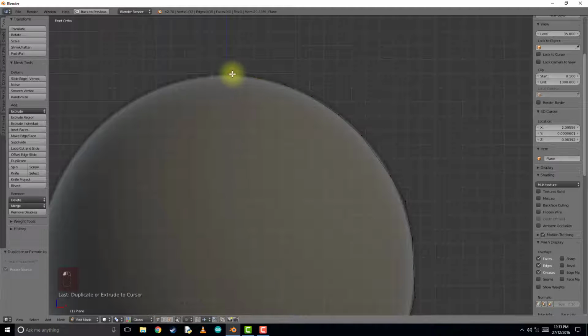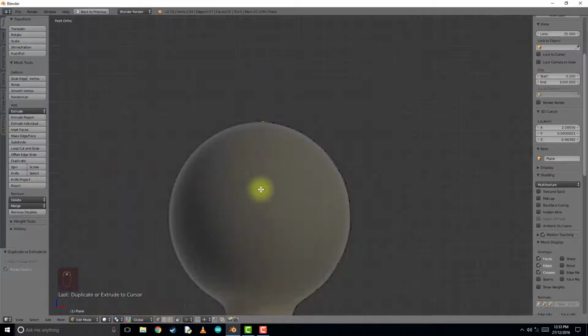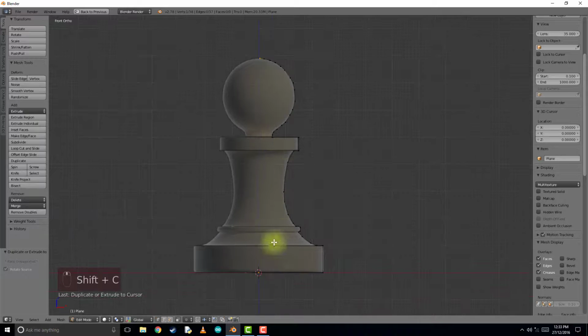This last point here has to be along this Z axis exactly. Now we push Shift C, we know this cursor is on the Z axis, so it's at X equals 0, being this side minus, this side plus. If I want this point to get right to X equals 0, or where the Z axis line is, I can transform this polygon to this cursor, pushing full stop to use cursor manipulation, and scale it along the X axis to 0.